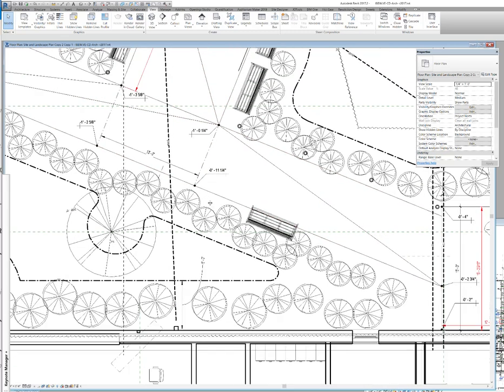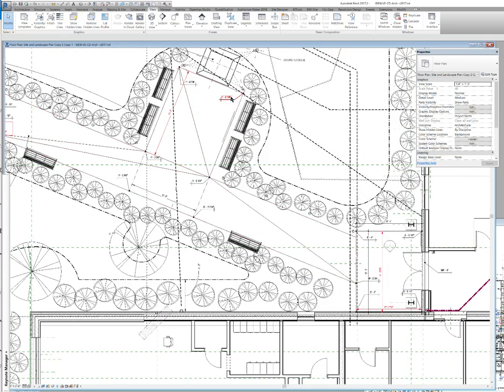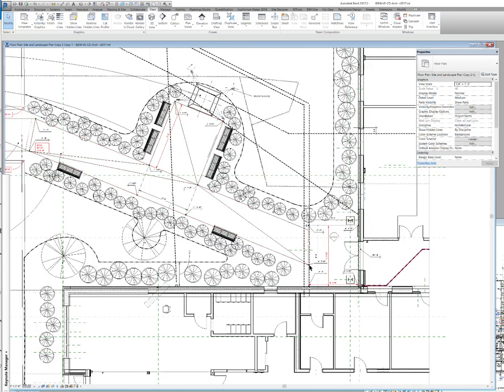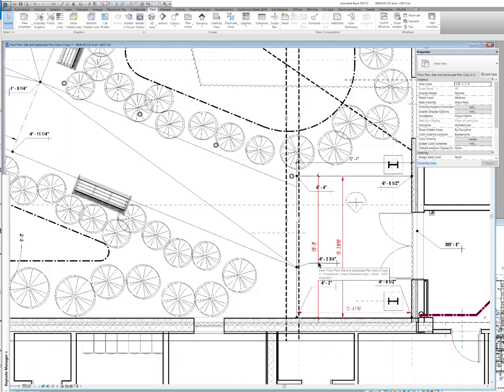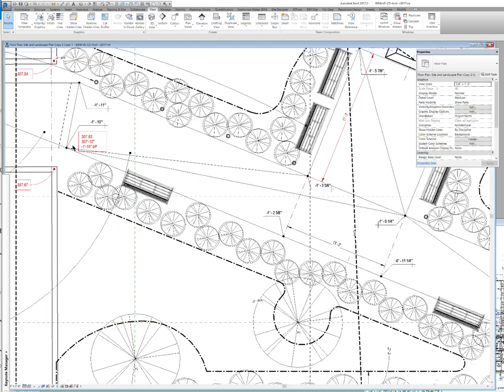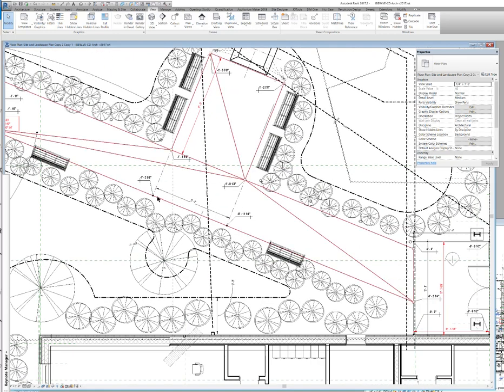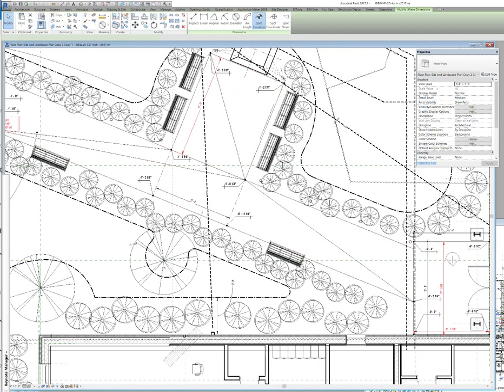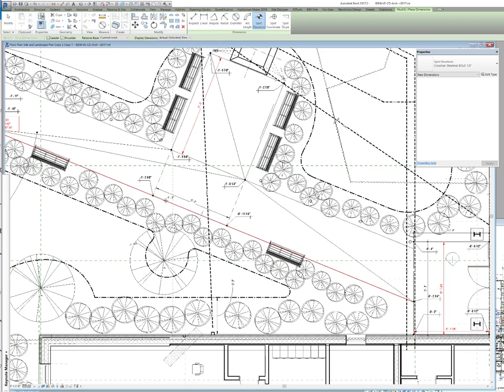Okay, so then I want to set this point, this point, this point, and this point. And that's based on, you can see there's nothing folded here. This is a straight line slope from the negative 2 3/4 inches to the negative 1 foot 10 inches. So if I just click on this with an elevation in the middle, this will tell me, and you notice, see, it's kind of sloping right along. So if I click on this, I already did it, I get 1 foot 2, in this case, at 5/8.